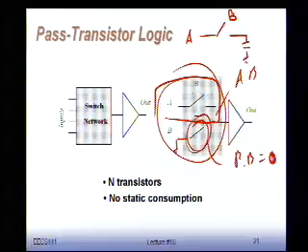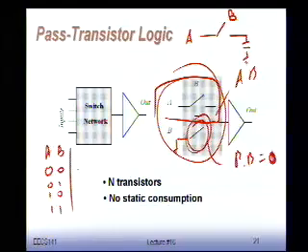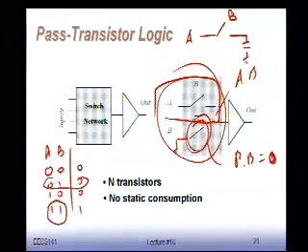So this ensures that under all conditions, our truth table is either a 0 or a 1. If you look at the truth table, you have A, B, 0, 0, 0, 1, 1, 0, 1, 1, 0, 0, 0, 1. So this is implemented by AB. When B is high, this is also defined. And this B B bar combination implements those two lines of the truth table and ensures that we're always going to get a 0 there. Okay? Because B bar is low at this particular point in time.